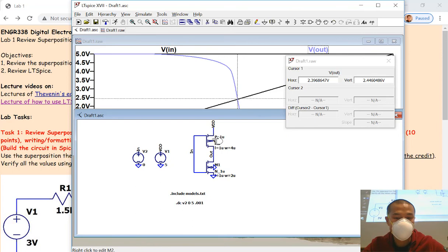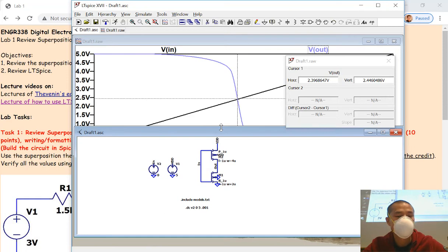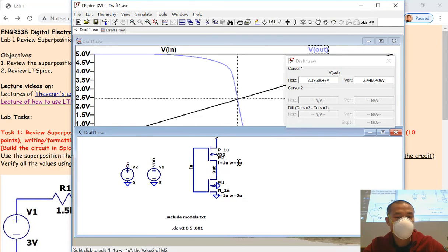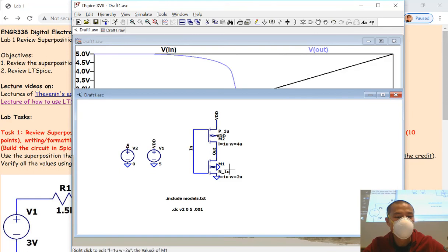And so they have a different capability of opening up the channel according to the input. So that's why the PMOSes are usually weaker compared to the NMOSes. That's why you relatively need a wider PMOS in order to make the switching point right at the 50% of the entire voltage range. So switching at 2.5. So that's a quick example about how to use LTspice, and also you can create a symbol out of it, doing a very similar job compared to Electric VLSI.